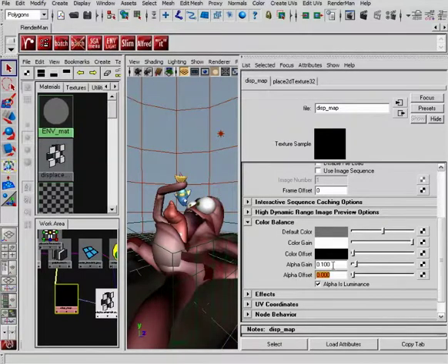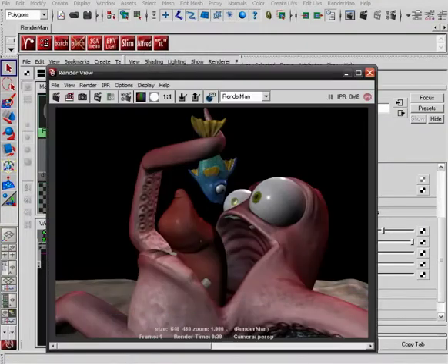Anytime that you're working with ZBrush, whatever this number is, you want to make the offset half of that, and you want to make it negative. That resets the black point. All right, so now that we've got that done, let's re-render. Oh, actually, we need to make this half, not 5 times, 0.05. There we go. All right, let's re-render this. Okay, we got some images coming back here. So let's take a look at what we have.